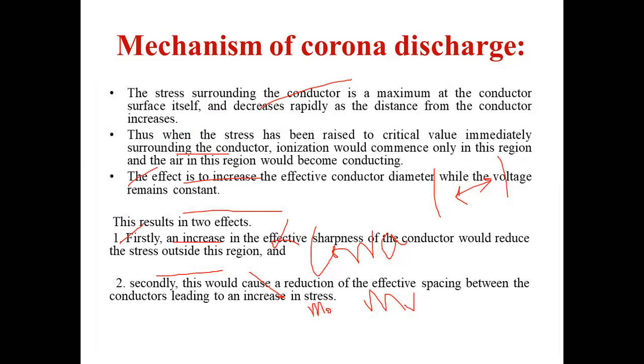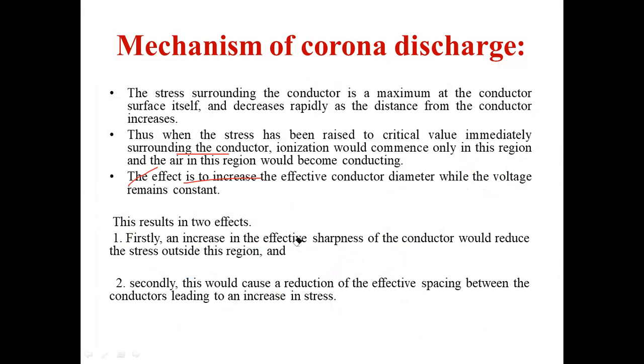Now, the mechanism of the corona discharge. The stress surrounding the conductor is a maximum at the conductor surface itself and decreases rapidly as the distance from the conductor increases.